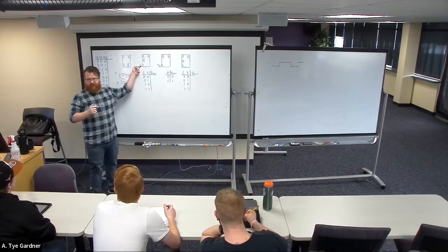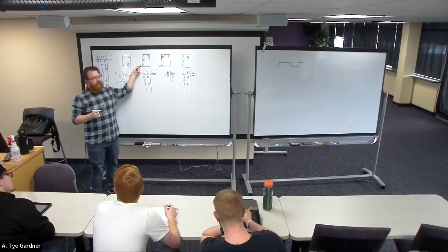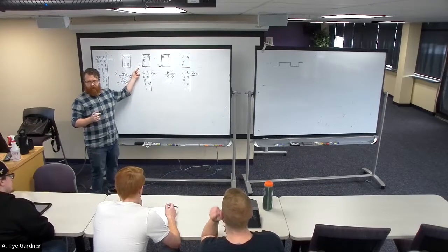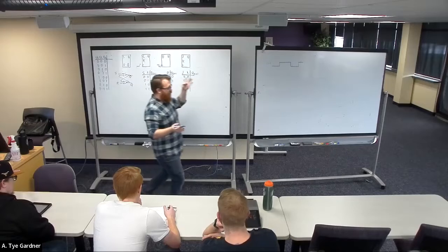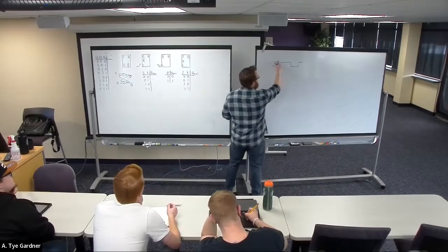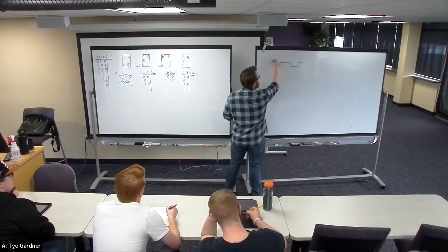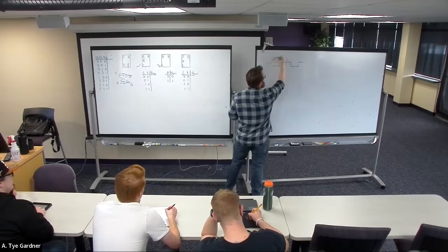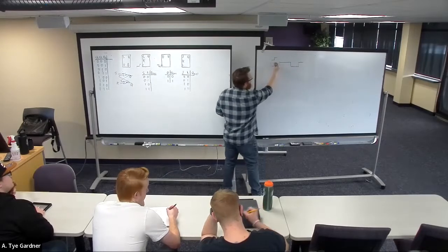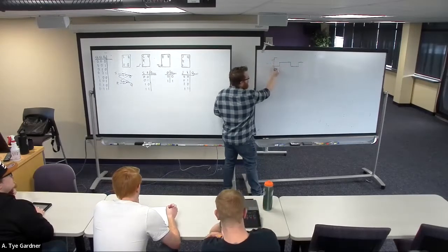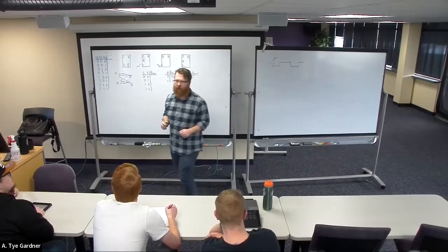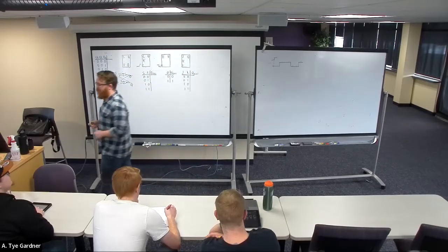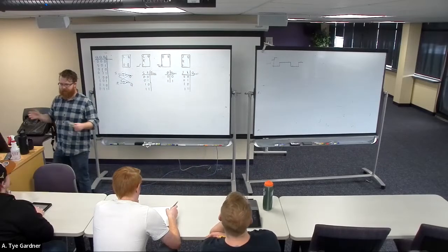That's what this little flag says, is it's expecting a clock. And it will change on the rising edge. So if we were to have a clock for this one, well, that clock is going to get, right? This rising edge would correspond to that first 0. And then we'd have 8 clocks in that if I wanted an 8-bit character.